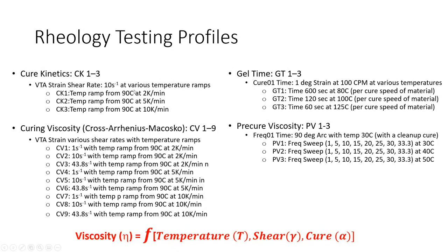But what the algorithms do, because the rheometer itself is subject to the thermal heating of the sample, right? I mean, if you used a sample that had twice the mass, I'm sure that the heat capacity of the material would cause things to cure a little slower because the material would soak up more heat from the metal surface, the hot metal surfaces of the system.